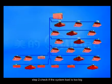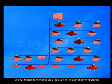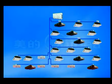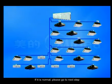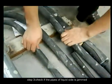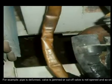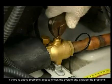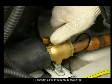Step 2. Check if the system load is too big. For example, the system is running in cooling mode under high ambient temperature, or overmatching of the indoor side leads to high evaporation temperature. If so, you can turn off some indoor units to decrease the running load, or add some outdoor units. If it is normal, please go to the next step. Step 3. Check if the pipes on the liquid side are jammed. For example, a pipe is deformed, a valve is jammed, or a cutoff valve is not opened, and so on. If there are the above problems, please check the system and exclude them. If they don't exist, please go to the next step.